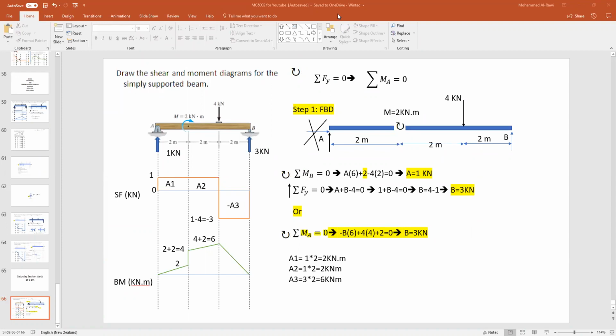There is another question. Why isn't it like a slope? Yes, good question. This is a rule: always, when we have moments at a point, we don't take them as a slope. We take them as a straight line. So they don't go horizontal. They go only vertical, either upwards or downwards, depending on your assumption. Moments at a point, we always draw them as a straight line.